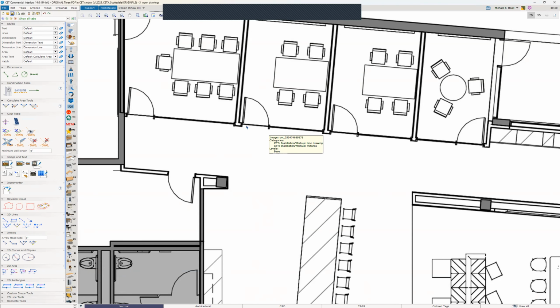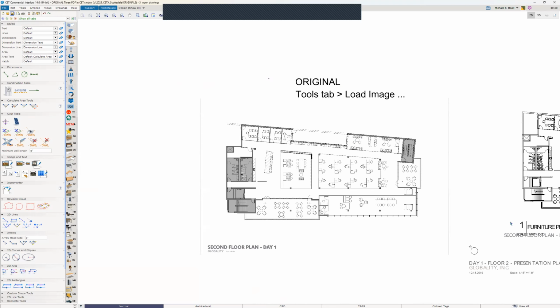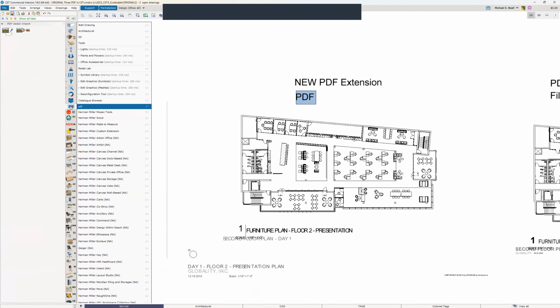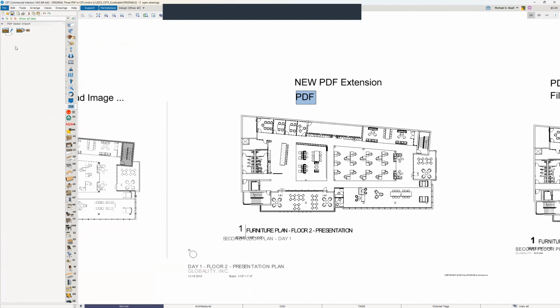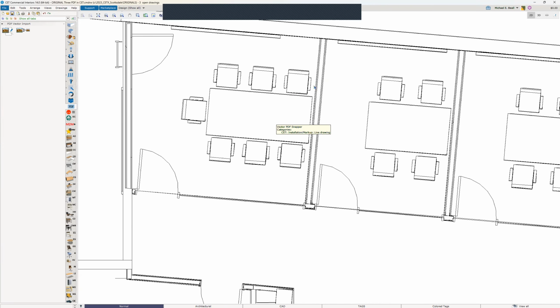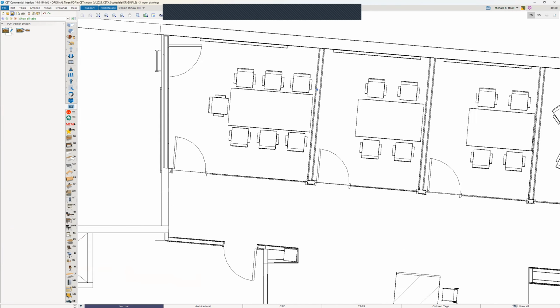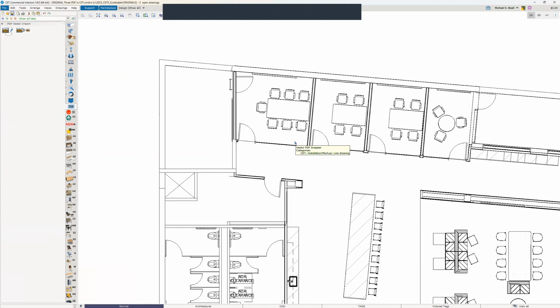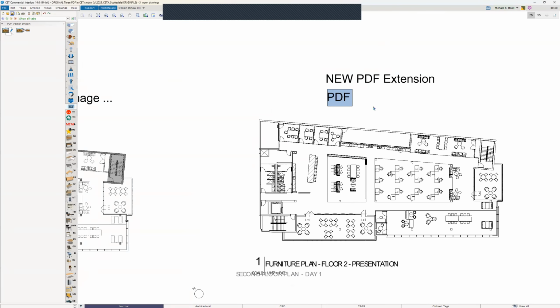Okay, so that's just Joe Bob PDF. That was the old days. New days, new PDF extension. There's a new PDF extension right there. And if you bring it in this way, it's the same process. You click it, you double click it. Look at the clarity that is much higher in here. So if you're going to bring PDFs straight off the bus into CET without stopping at AutoCAD, then you want to be using this new one with this little image.